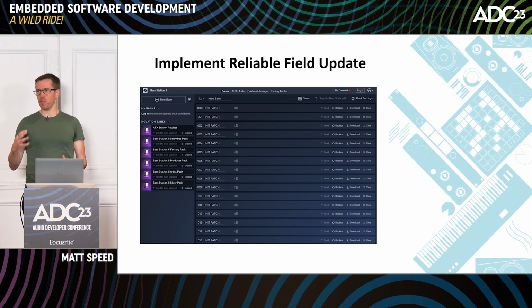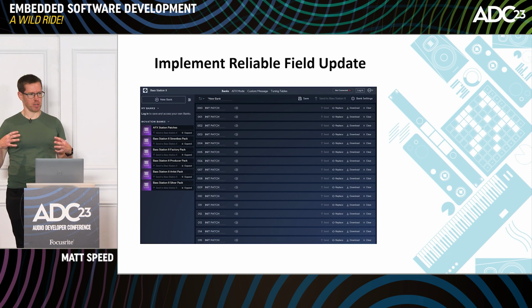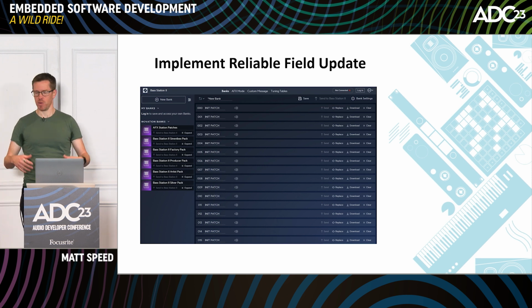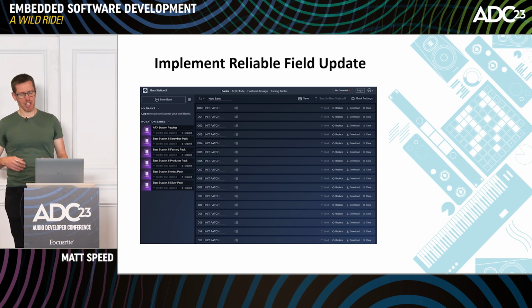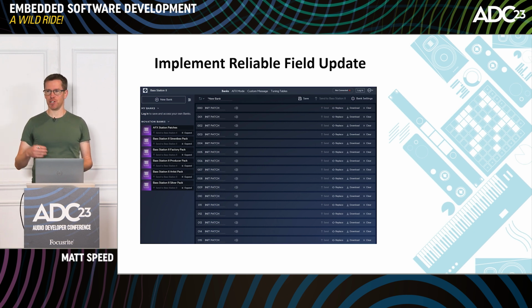It's that little blob of firmware that is as atomic as possible, that you never want to change, and it just has to always be there and always bring the device up from its useless bag of transistor state into something we can use. It will typically have some view of a firmware binary, and when you want to upgrade, it will replace it and then know that the replacement has been completed successfully. So if a firmware upgrade fails, the bootloader should observe this, and it should be able to fall back to an earlier version.